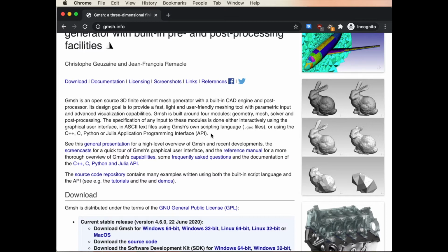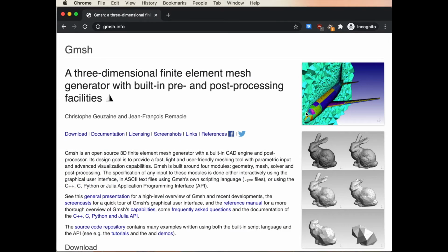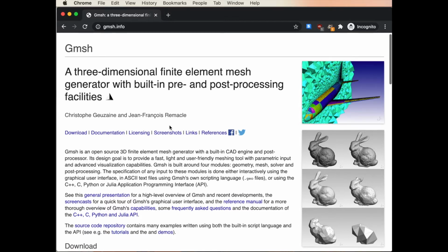So when I'm talking about GMSH or related grid generation tools related to the class, we will basically look at this as a pre-processing tool where we can have a CAD engine, we can have CAD cleanup, like is shown in these figures on the right, and then create three-dimensional or two-dimensional geometries on the surfaces and volumes. So this is what we'll look at.